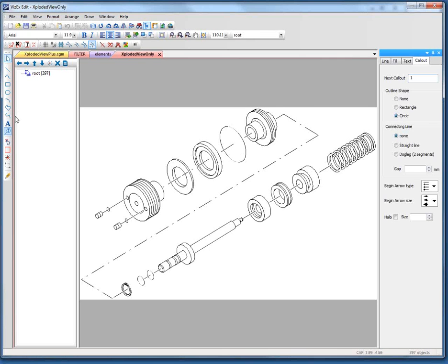I want to circle around my callouts. So now I go over to the left to start the actual callout annotation, and I select the callout, add callout tool, and I anchor it first to where I want to position it. Oops, I see I have my snap to on, so you noticed it snapped to the center of that little ellipse down there, but I really didn't want that. I wanted to,